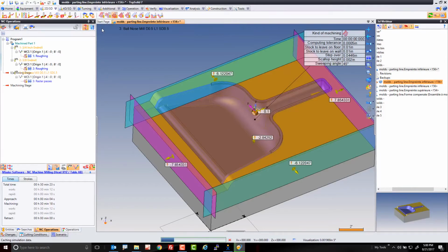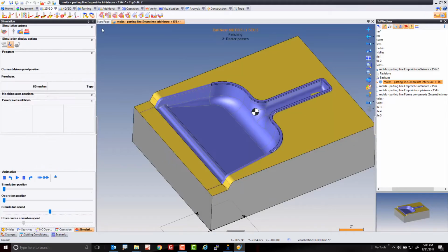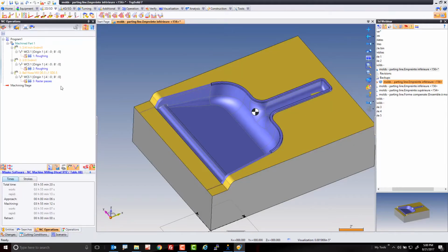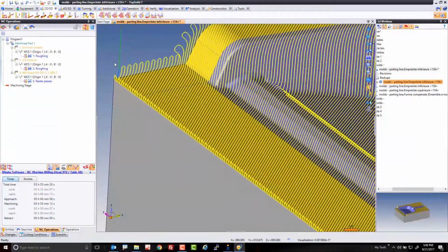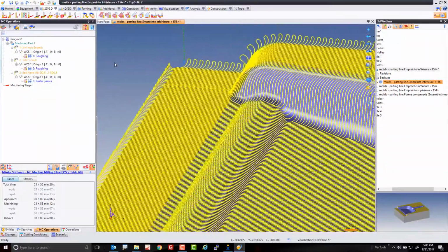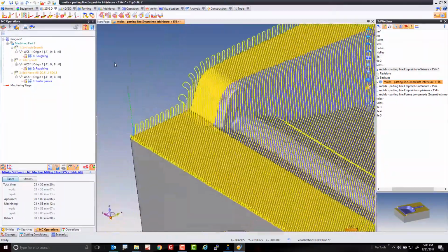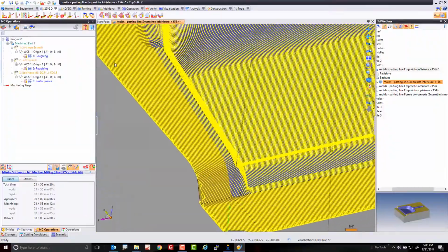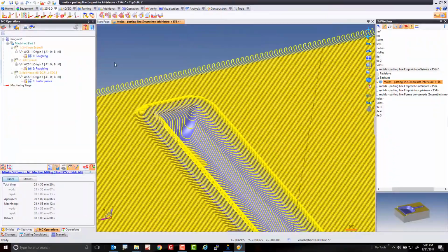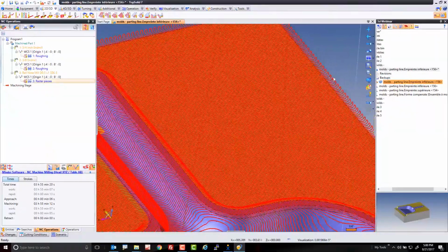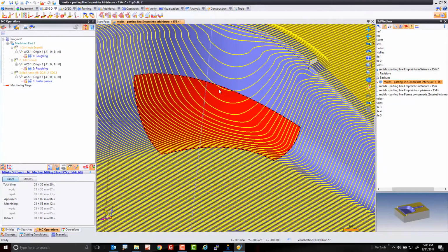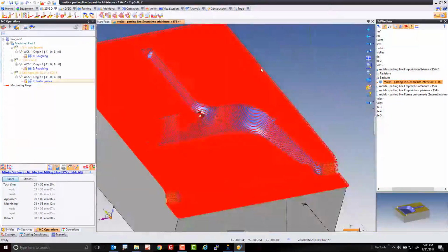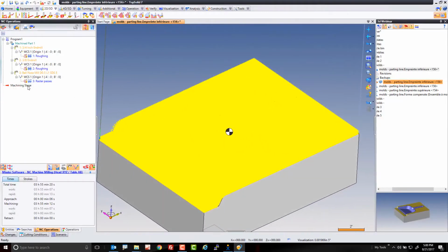Now here, TopSolid is going to apply a raster pass, but again, I have some default values set. So when it makes that raster pass, it's going to have all of the cool features that TopSolid handles turned on and activated and set to calculate appropriately based on the tool selected. So here you can see I'm doing a nice little smooth move, a little raster pass just to semi-finish this thing, knock everything down. You have nice clean dogleg loops. Anywhere there's a sharp corner, we have filleted the toolpath if possible, just to make it even smoother motion. And again, all you had to do was pick a tool and hit go.